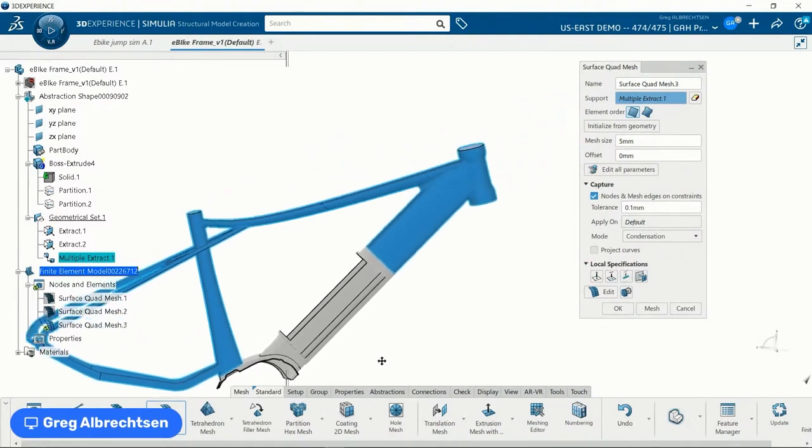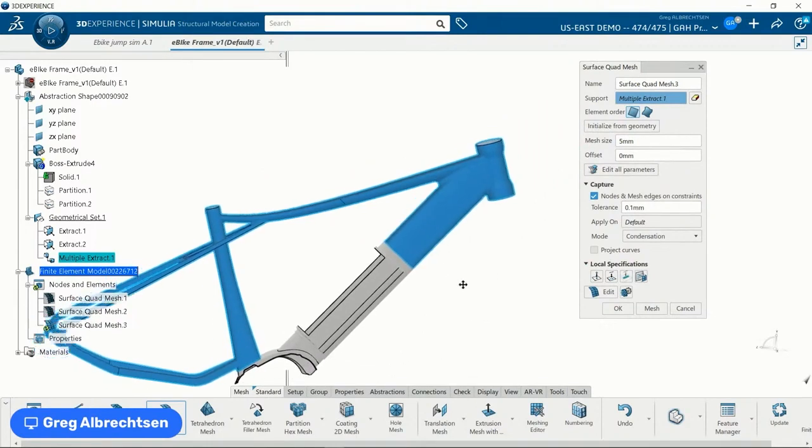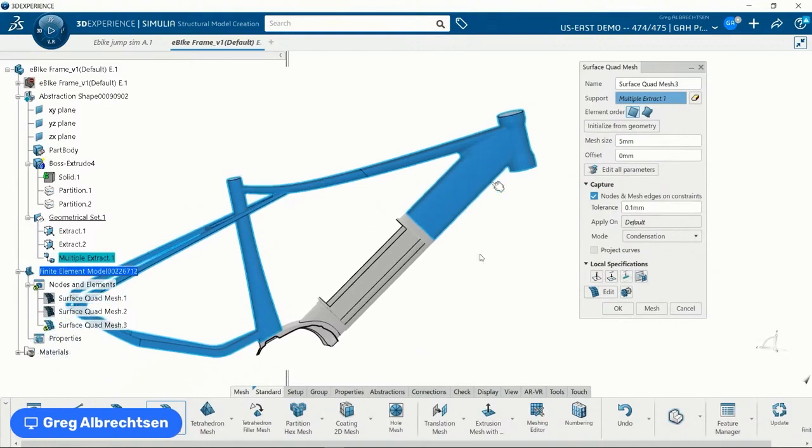Now, if we're very, very concerned with the stresses here, maybe this could be another session, but I would go ahead and shell mesh this. What you can then do is extract those displacement results from the shell mesh, and you could apply those in a more detailed mesh.